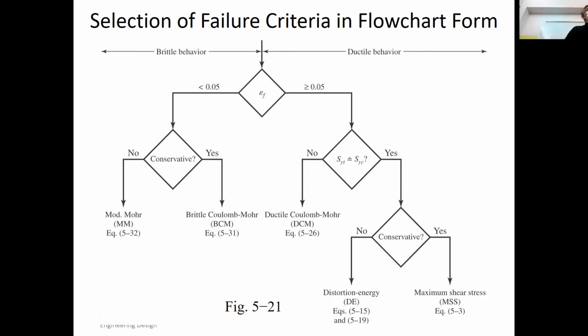If you want to think about it simply, if you look at brittle material like glass, concrete, they can handle way more compression than tension. No wonder our civil engineering fellows have come up with this composite material ideas decades ago by reinforcing their concrete, because their concrete can only take compression, but it always fails in tension. So they add this reinforcement to allow it to handle tension. Right? So brittle material, definitely the answer is going to be no. But for ductile material, mostly yes.